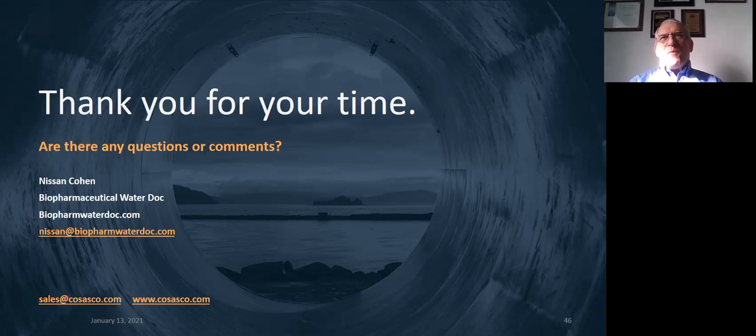Again, Rouge can develop very slowly or fairly quickly, depending upon the components that are in your water system, the temperatures that you run at, whether you're running at 80 or 85 degrees C continuously, etc. So not all water systems are going to Rouge at the same rate, but you perform your derouging passivation by gauging a value that you want to determine. If I determine that 400 nanometers is the value that I want to do my derouging passivation, and I'm only running at 60 or 70 nanometers per year, it may take me 5-6 years to get to that level before I do a derouging passivation.